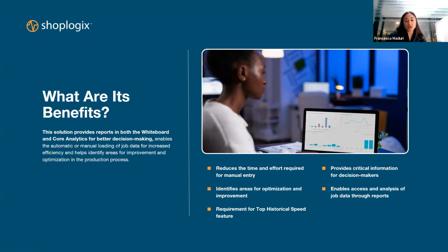But Brock, can you walk us through some examples of how a customer might benefit from adding job data into Shoplogix? Yeah, the one thing would be, especially I think maybe from a financial operational viewpoint, is we talked about having rate as a requirement. So if I have the rate as a requirement, when the corporate standard came out that I can run, say, 62 pieces a minute, on this line for this product, that may have been when the machine was brand new and the tooling was brand new.